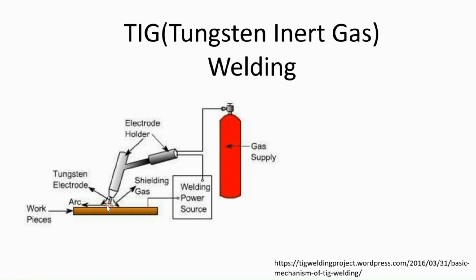So how is plasma produced? You have some electric energy that is exciting the gas molecules in this region, and they are ionized. When these ions take in an electron again, they release a form of energy, as the gas molecules come back to the ground state. You can look up what plasma is. Ultimately, what I mean to say is that this plasma is what is producing the heat in this region.